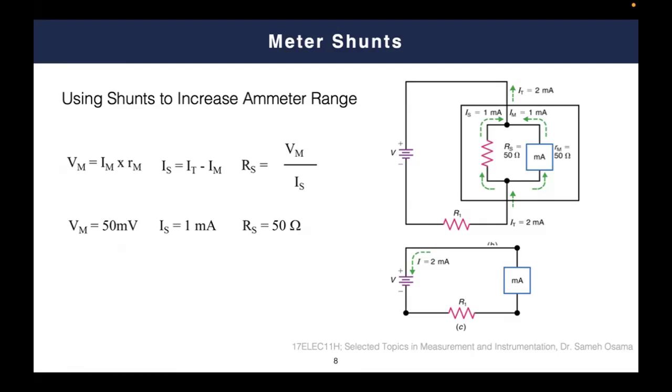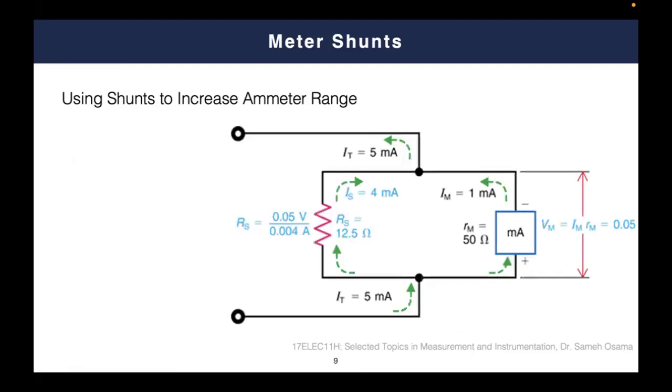So this is typically how we can extend the range of an ammeter. Let's have another example in the same direction. This is again a restricted value because this is simply the coil. You are not going to change the coil. This is the fixed ammeter coil. Here the coil is with 1 milliampere current and still 50 ohm resistance. So again, the voltage drop here will be 0.05, which is 50 millivolt.